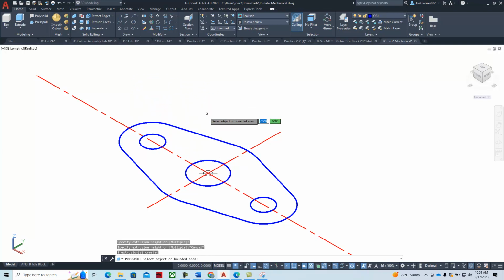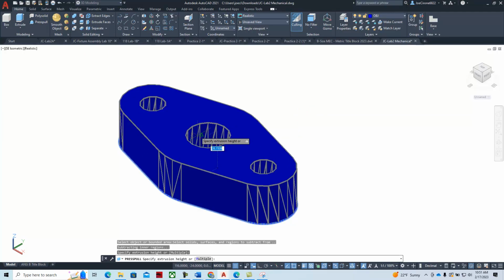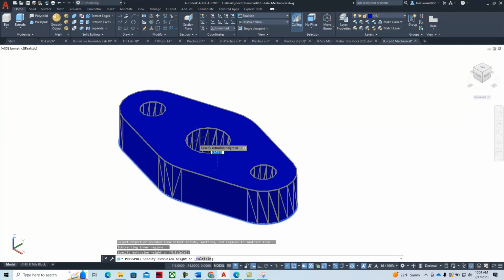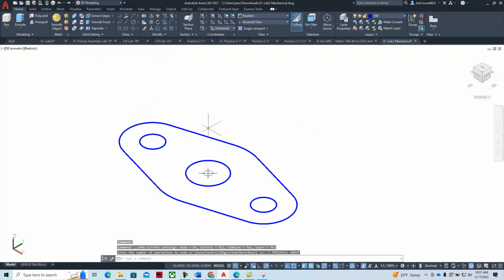And yes, you can union them together and put it together, but we're not going to do that. So I'm going to delete this out, as well as this. I'll do my detailing and annotation at a different point. This is just a point. I like to leave it there. It's not going to make any difference. And then press pull is a more efficient command. So if I press pull it and then I bring that up 12, we're good to go. We're pretty well set. I'm going to undo that. And then I'm going to do that again.